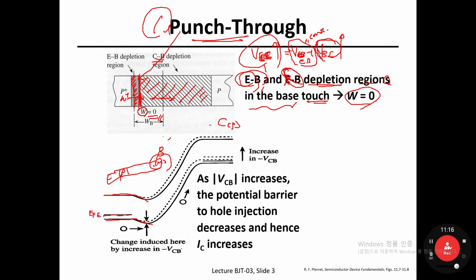Then on the right-hand side, let's draw another energy band diagram for the PN diode under reverse bias. So this is the P side conduction band edge, and that is the conduction band edge in the N side under reverse bias. Reverse bias means the P side has been moved upward and the N side has been moved downward. If I connect all the conduction band edges, then you may draw the energy band diagram for this PNP BJT device. Again, the emitter-base junction is forward biased and the base-collector junction is reverse biased.